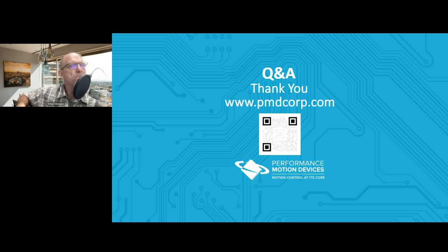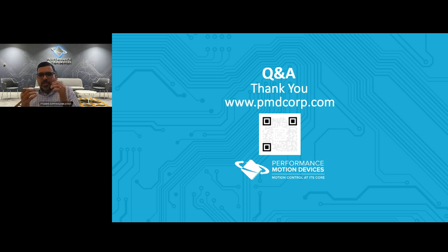Yeah, so what we tend to do on the chips and the drives, we call it UDPM, user-defined profile mode, where, say a mobile robot has to go from station A to station B. It could be a whole bunch of moves, right? It has to traverse a bunch of moves. So instead of the master commanding it for every segment, you can load a table. So you can actually load a table with a whole bunch of points that the robot has to traverse. So at the end of that whole path, it'll give an acknowledge saying that path is completed.